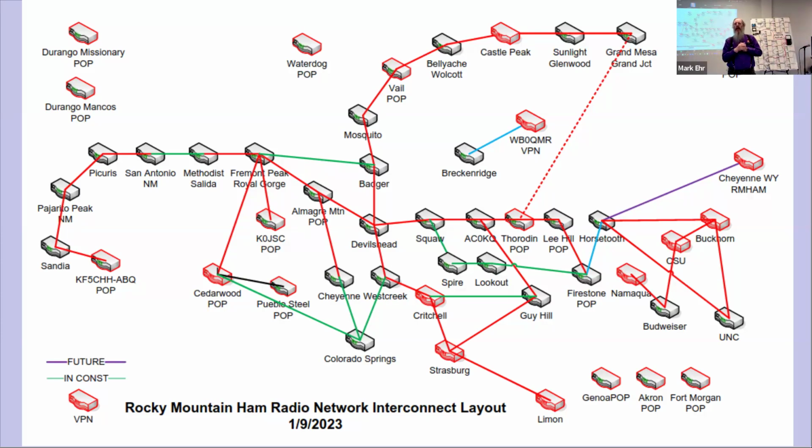And so how you'll hear that is, you key up on the connection, you say, "Hey, this is AC0KQ," you unkey, and half a second later, you hear yourself, right? So it went to the main site, was retransmitted from there, and then you hear that. So you can buffer for that kind of delay. On the other hand, P25 systems were designed to use telephone lines where there's very little delay. That's at least version 1 of APCO.